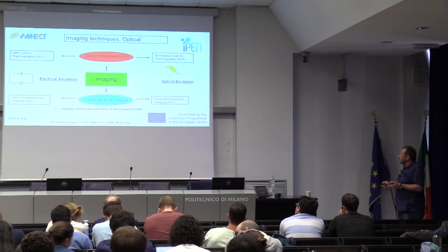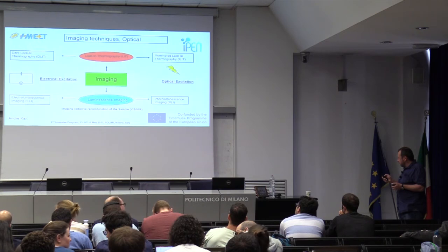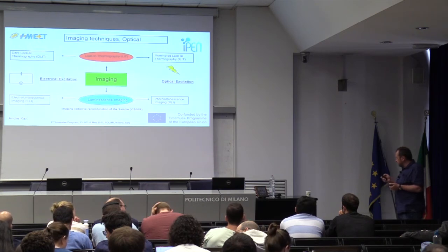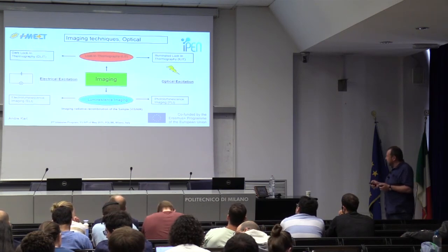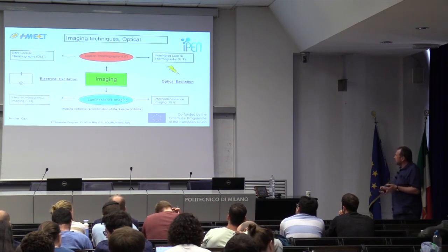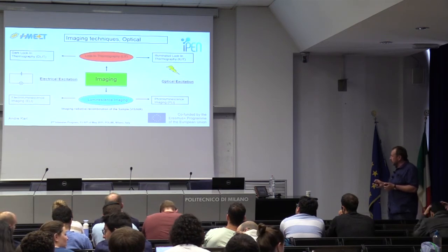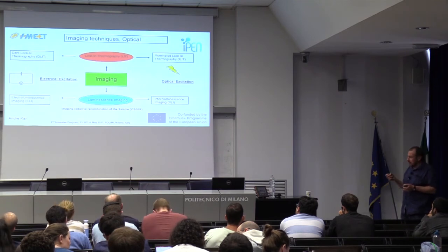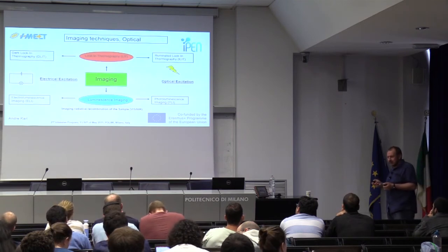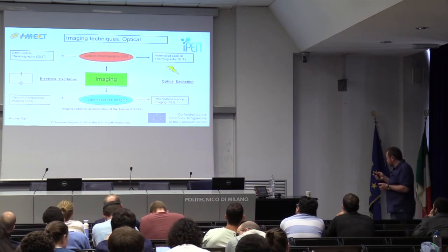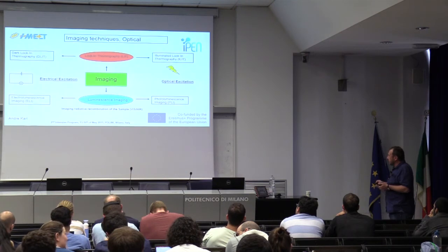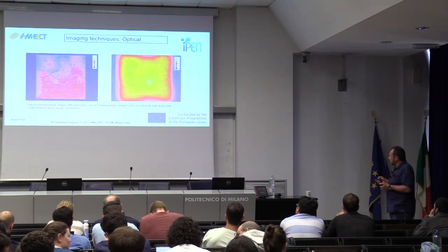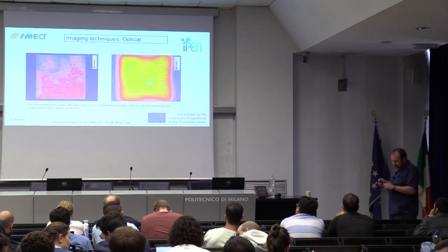But now there are further imaging methods. This is a slide from André Karl, who is actively doing this. You can use dark and illuminated lock-in thermography, so you see the shunts, you see which parts of the solar cell get hot. And you can also do, in addition, electroluminescence imaging and photoluminescence imaging.